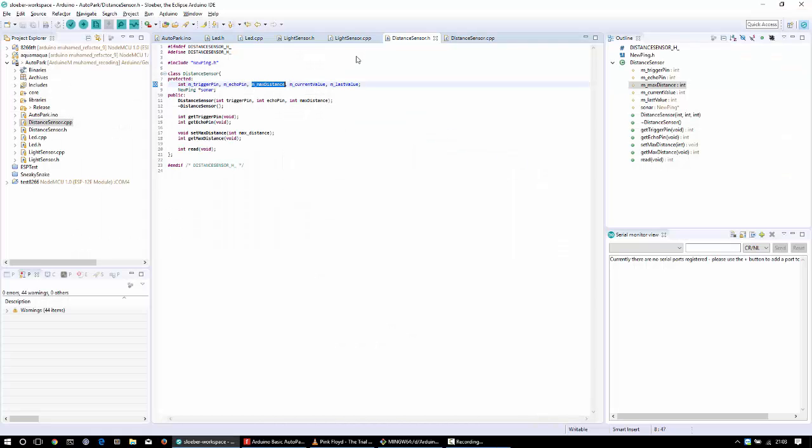That's variable for this new ping library, it needs to know what's the biggest distance you need to calculate. I mean, if you don't need bigger than 100 centimeters, in this project we don't need that. We need maybe 30 centimeters or something like that.